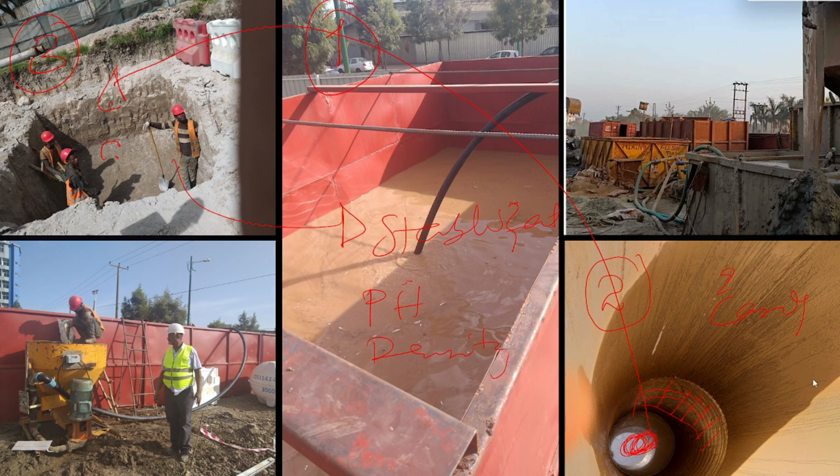We also prepare the septic tank to manage and mix the slurry. After excavating a temporary storage near the bore pile, we recycle the slurry and transfer it back into the mixing septic tank to process it for reuse. Before pouring concrete, we ensure the slurry is at the proper mix ratio by conducting density and pH tests, along with other testing methods. Finally, we apply the slurry into the borehole to prevent soil collapse, which can compromise the pile's strength. This is where we apply our slurry material. So proper configuration of this bentonite ensures a strong